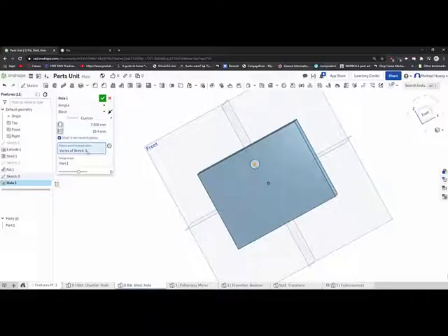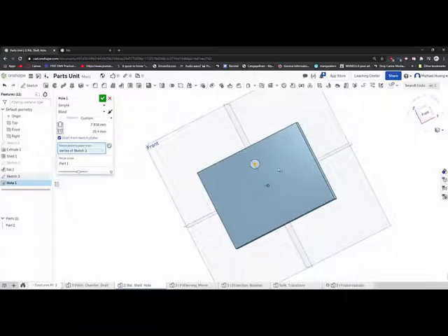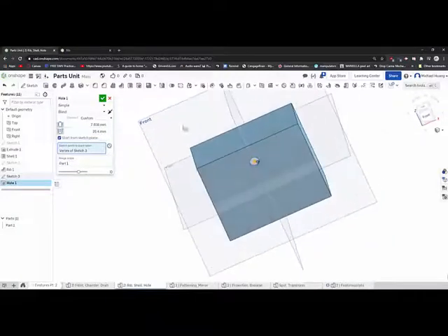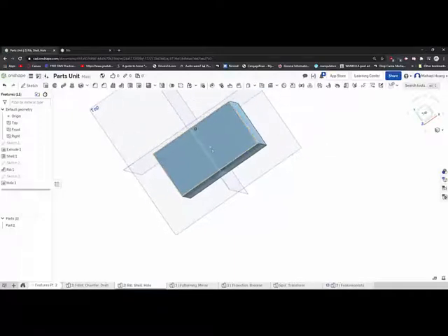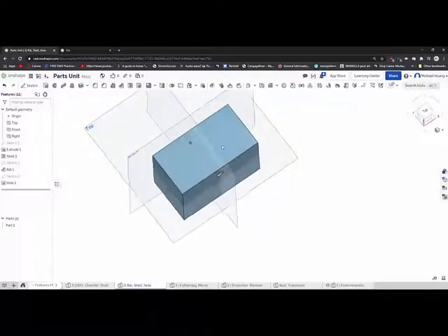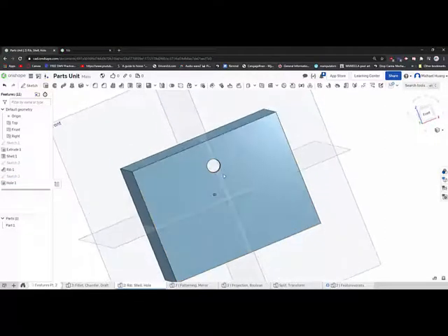And there you go. Now, you could just extrude it, right? Draw a sketch for a hole and extrude it. But the hole is useful because if you're required to make more than one hole, and there's a number of different holes here, it's very easy to change the properties of your holes. So you can change the diameter and your depth here, right? If you have multiple sketches with extrudes, then you're going to have to go into every single extrude and edit the extrusion values. The hole is just much easier for this purpose.